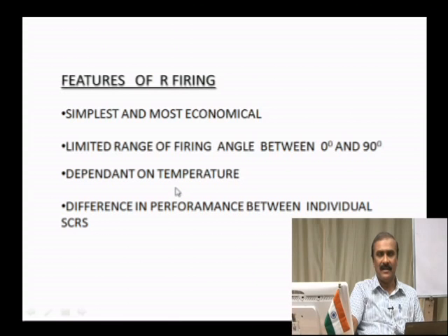Dependent on temperature, yes, because it is a resistance. Whenever current flows through the resistance, temperature increases, and the variation in temperature causes variation in triggering also. So, these things are to be kept in mind before you use these resistance firing circuits. Then you can see another important one, the difference in performance between individual SCRs. It will not be the same, so you have to design a separate circuit and separate values for different SCRs based on their requirement. So, this is all about the resistance firing circuit.